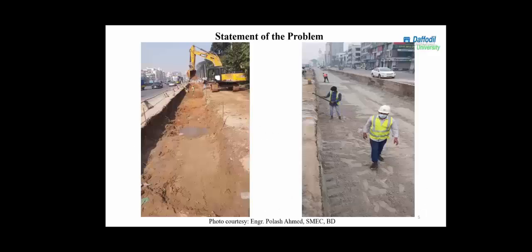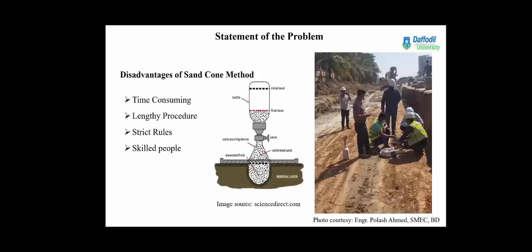Due to the poor quality of subgrade soil, most of the pavement works require an improved subgrade layer in Bangladesh. The improved subgrade layer is required to be compacted to a relative compaction of 95% and above compared to the maximum dry unit weight measured in the laboratory by standard or modified Proctor test. After compaction, the quality is controlled. That means field dry unit weight is measured by means of the sand cone method. But the sand cone method requires both field and laboratory measurement, hence it is time consuming and uneconomic.